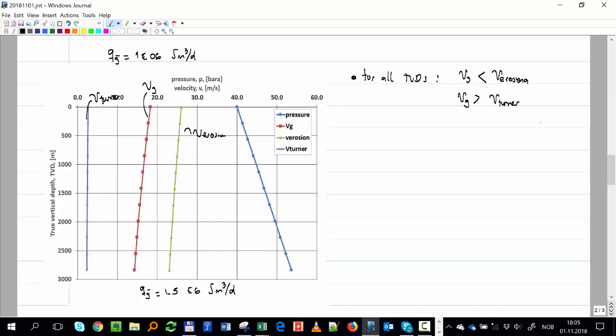Sometimes in the tubing you have scale. Like in tap water, in the shower, sometimes you have formation of this mineral, like a white deposit on the shower. The same thing happens on the wall of the well, it starts to accumulate and then reduces the diameter. So it could be that you're using the original size, but it's also reduced. Yes, the properties of the gas might not be correct, but in principle, it should give you a very close result.